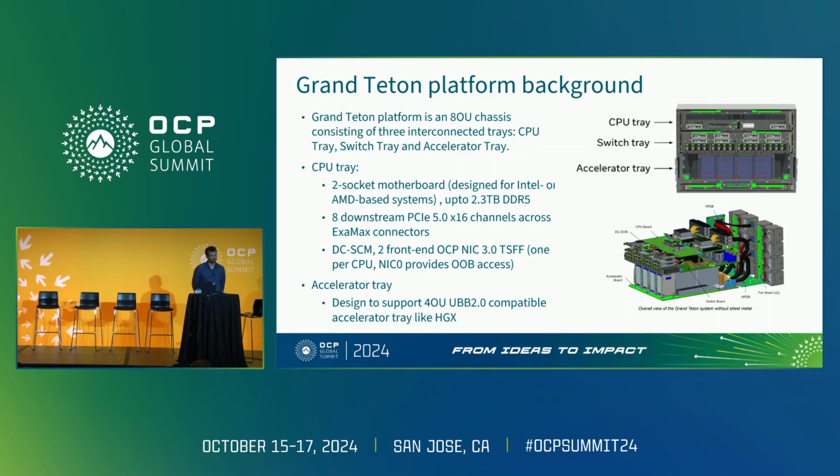Maybe you can comment a little bit on the CXL ecosystem, and if you validated the system with CXL, and if all of the firmware, software, everything is in place already, that would be good to know. Yeah, we did validate and qualify the DDR4 based expansion. In our superset config, we basically have 2 TB on the host and 1 TB on the CXL, and that's something that we've tested. Great, thank you so much.